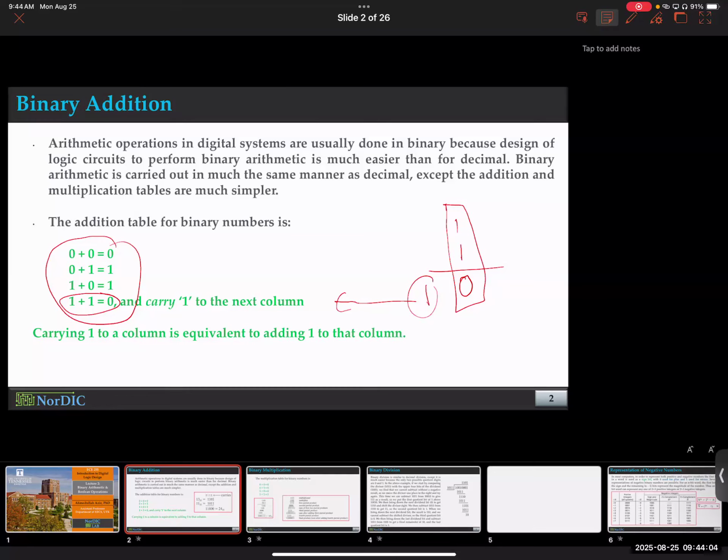Imagine you have a certain bit system in your hardware, like an 8-bit system. You add two binary numbers, both 8 bits, and then you generate a carry which gets to the 9th bit. Notice that the carry can require more bits than you allocated. Does that make sense? So when you design hardware, you have to be aware of how much carry your operations can generate. And that's how you design your memory size.